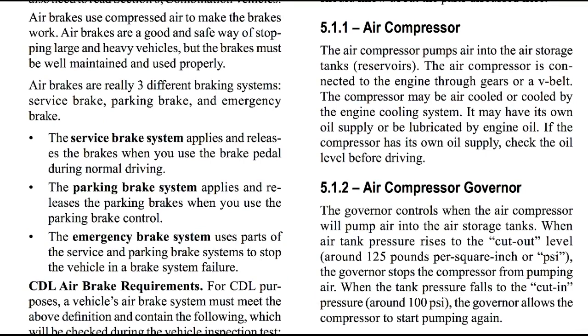Air compressor. The air compressor pumps air into the air storage tank or reservoir. The air compressor is connected to the engine through gears or a V-belt. The compressor may be air-cooled or cooled by the engine cooling system. It may have its own oil supply or be lubricated by engine oil. If the compressor has its own oil supply, check the oil level before driving.